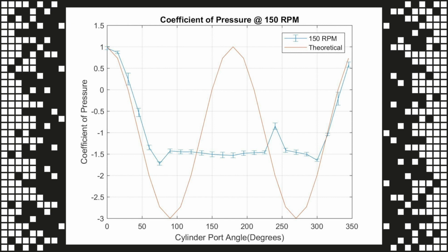However, the theoretical curve assumes inviscid flow. In reality, the flow detaches from the cylinder. As you can see on our plot, our data becomes a horizontal line near angle 90 or port 6. This is where the airflow detaches from the top of the cylinder. One of the potential reasons for error in our data is the turbulent vortex shedding creating differences in